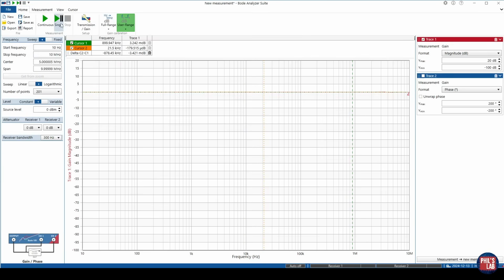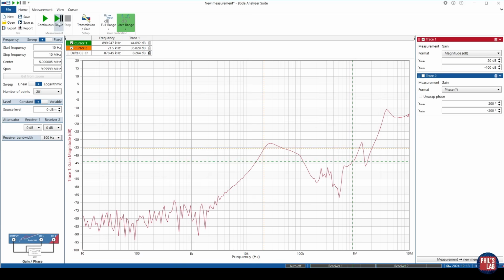Now let's perform a single measurement. Again, our input voltage is 9 volts DC, our output voltage is 2.5 volts DC, with 150 milliamps of current at the output. And now we have a plot of the power supply rejection ratio at this very specific operating point with this very specific regulator and with these very specific components around the regulator and of course the board design itself.